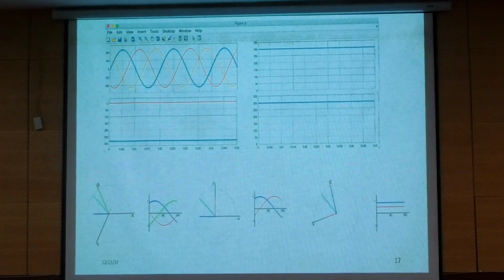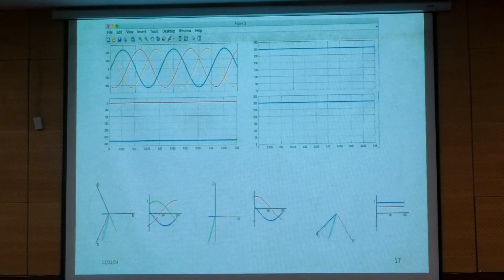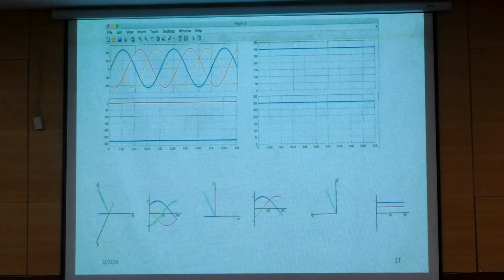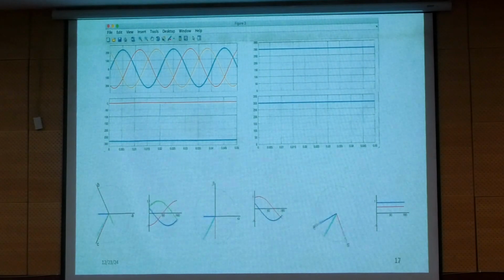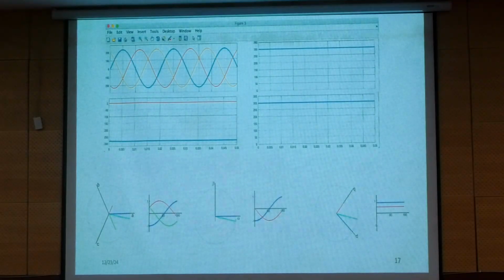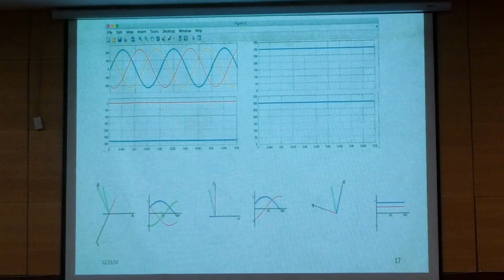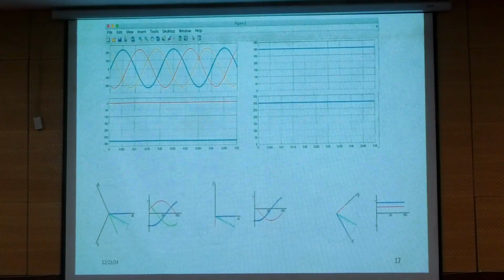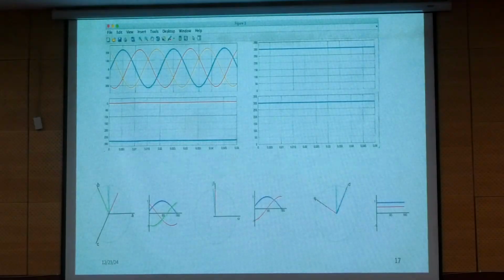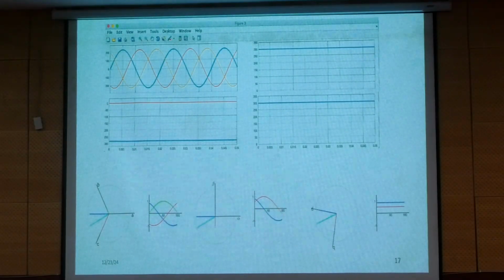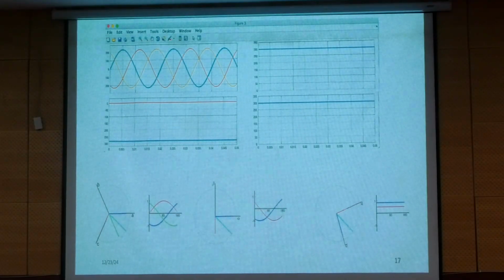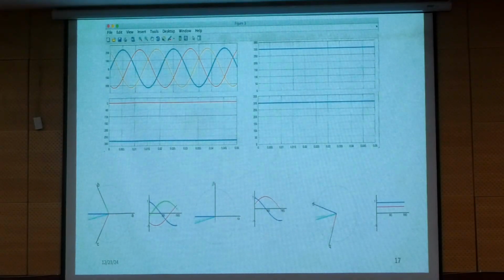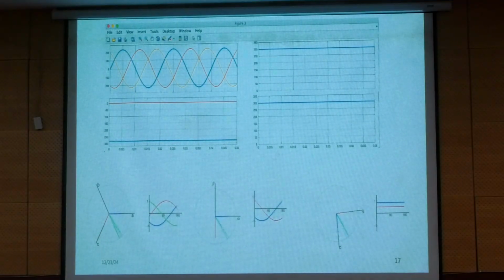See here, take the first waveform. My request is, in simulation you need to take 3 sinusoidal waveforms, right? Take 3 sinusoidal waveforms directly from the library itself. You can take frequency 50 Hz and magnitude 1, right? After that, multiply the signals with 2 by 3, take theta 0. If you take theta 0 you will get the cos 0 equation, the same equation you can take. Later I will tell from where you will get this theta. That is very important in FOC, right?